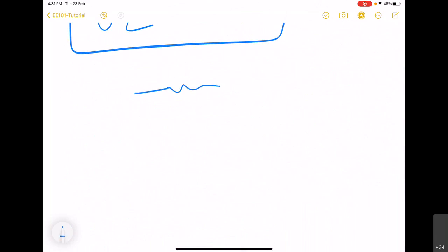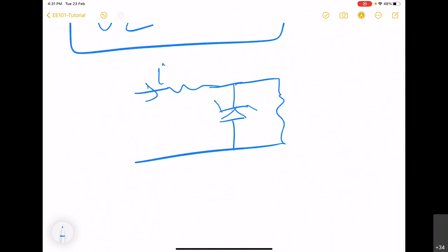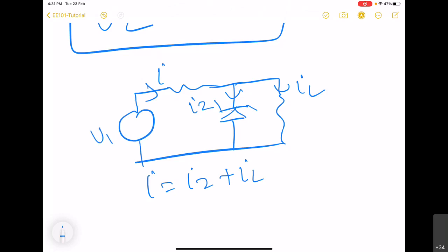So we have seen that whatever current is provided, this will get split into Zener branch and the load branch, Iz and IL. So I is equal to Iz plus IL. So as this input voltage increases, this current increases, and there will be tendency for these two currents also to increase in general. When this increases, there is possibility of increase of these two.